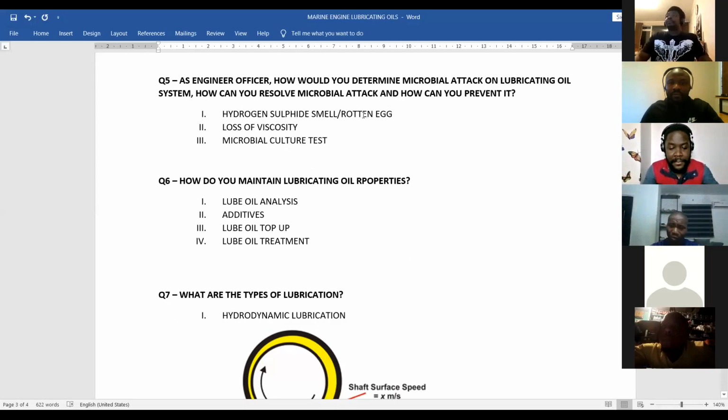And from time to time, you also have to take your lube oil sample. Sampling of lube oil is done and sent ashore for analysis. The concern there is that it is going to tell you how healthy your bearings are and probably your gears, your meshing parts. It's going to tell you whether any of them have been rubbing off.